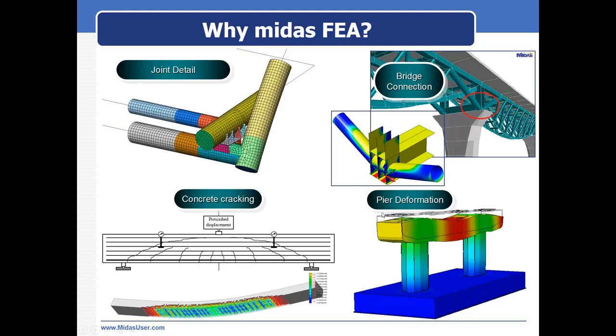Another application would be the pier deformation. Generally, when we talk about deep beams, solid modeling is very much necessary. If we go for frame modeling, then that's not that accurate. So for accuracy, we go for solid modeling of deep beams, and that's the proper approach. And there, FEA is quite helpful to the engineers.